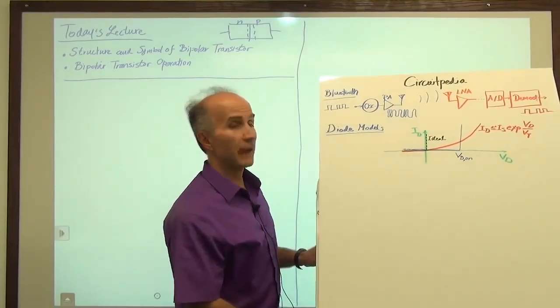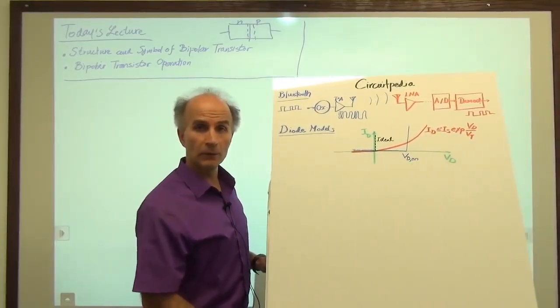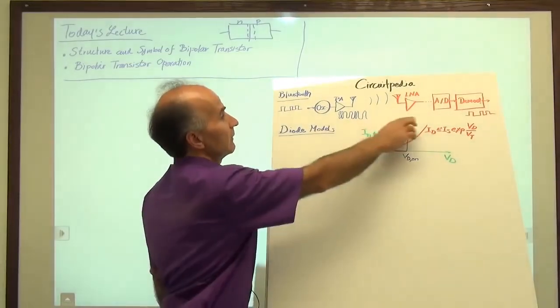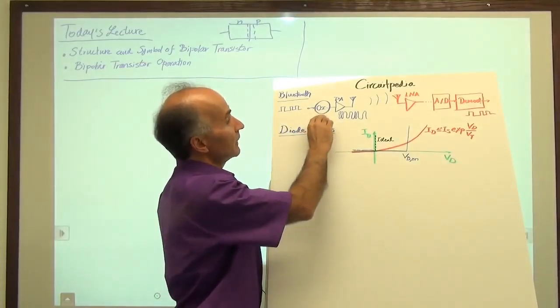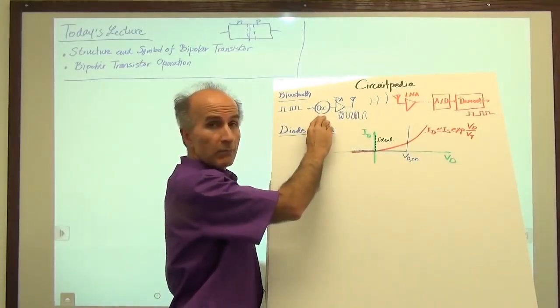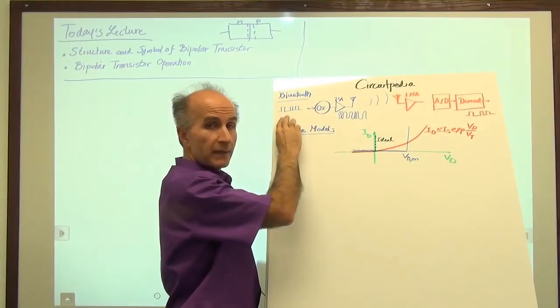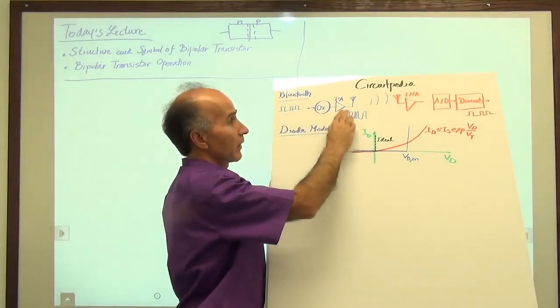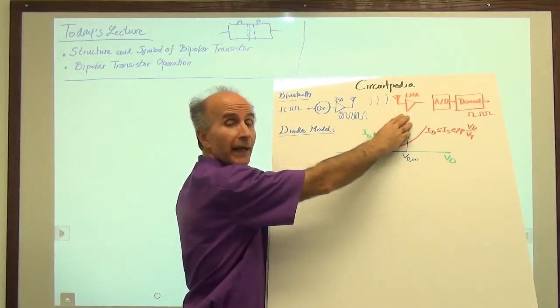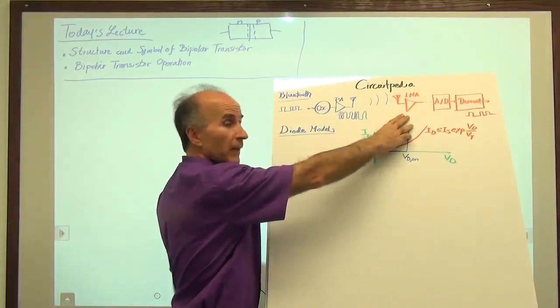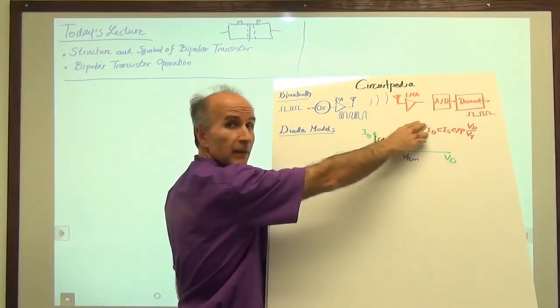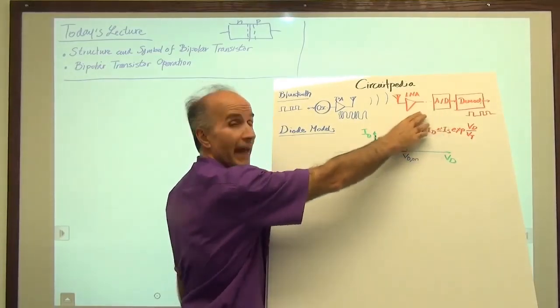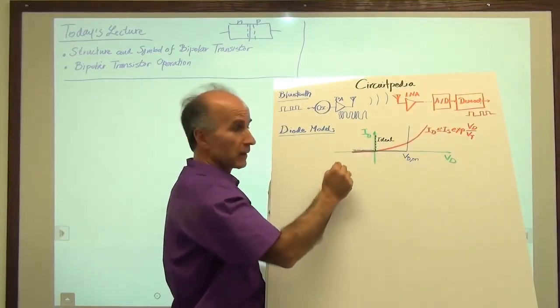Again, remember that when we designed the Bluetooth transmitter and receiver, we had an oscillator whose frequency was modulated by the ones and zeros, and then we had a power amplifier, and then on the receive side we had a low noise amplifier followed by some other processing, followed by an analog to digital converter, and then some more processing.